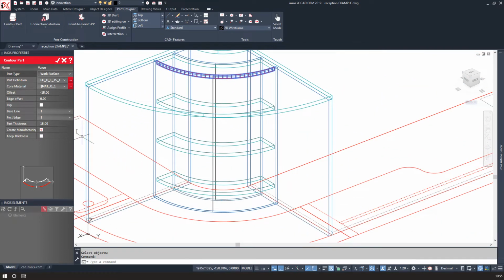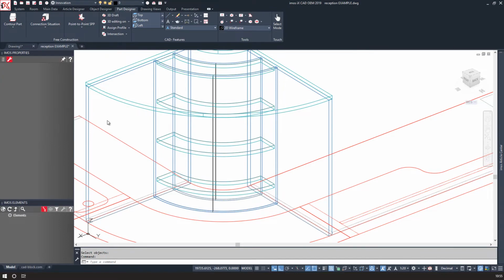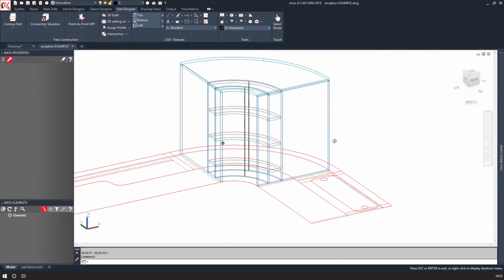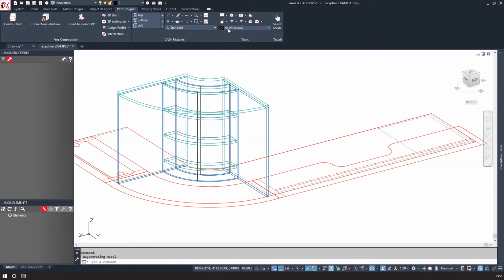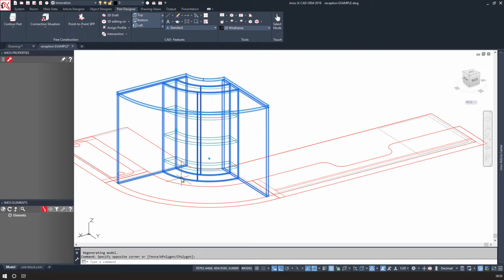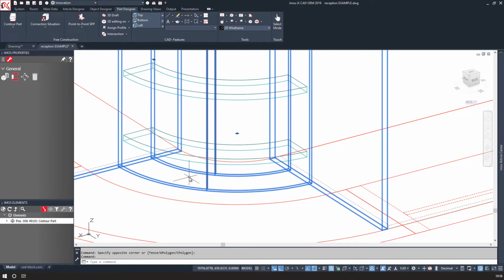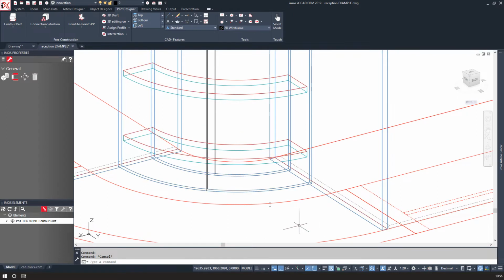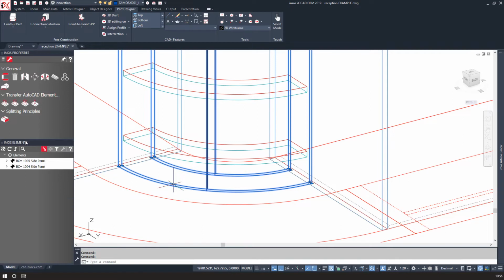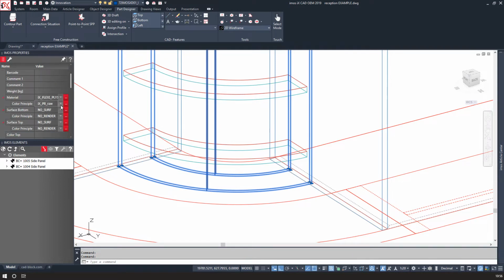So when it comes to assembling this piece, the production team can put some pins or brads, nails, screws through the 12mm flexi ply into these curved sections to help keep its form, and then over laminate this by hand. There's lots of different ways of creating these parts. I'll make sure that these have a laminate surface applied to them so that you won't see the screws.